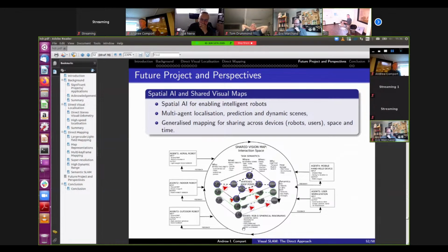For a depth sensor, it's a bit different because you're invariant to where that is transformed to, because the distance between 2 points in 3D seen from different views is always the same. Whereas the image error is projected in the image and depends on where it's been seen from.